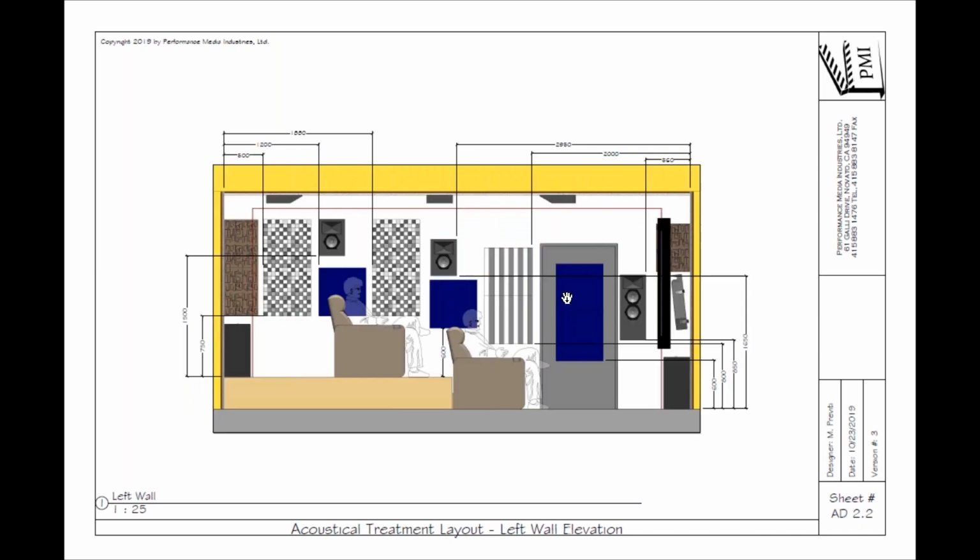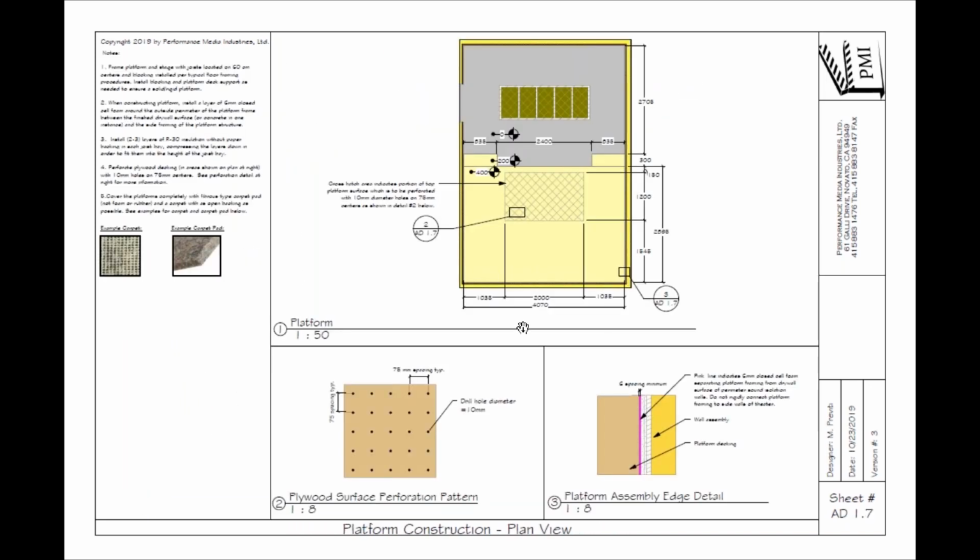But this room has an extra little trick that I didn't talk about, and I really want to conclude with, which is we were given the opportunity to put some absorption in the floor at the front. I call that an absorption pit. Very cool. You build the room with a recess in the middle to catch the first reflection off the floor, nice and deep.